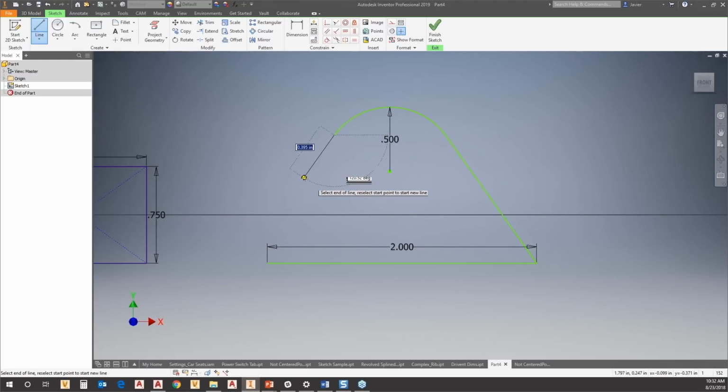Now, I want to tell it how to constrain very specifically by scrubbing. If I scrub geometry, if I put my cursor over it, you'll see I now get a tangent. It thinks that if I get in the right position at the right angle, in this case 127 degrees, I want to constrain to that. Well, what if I don't want to constrain to that?